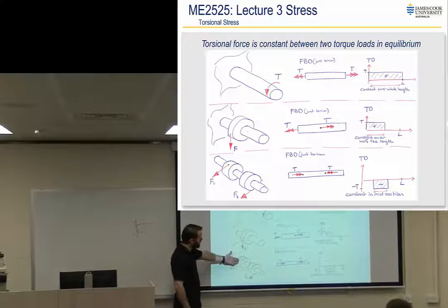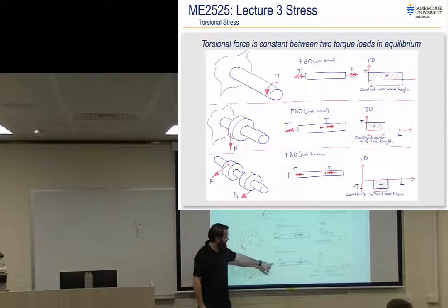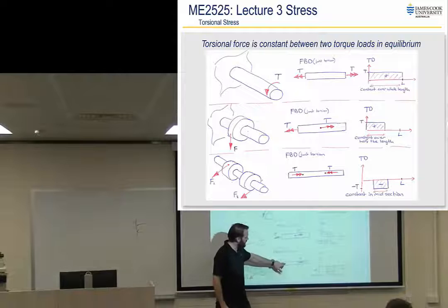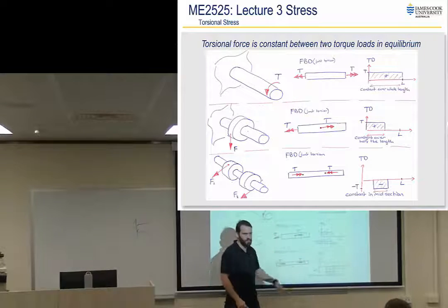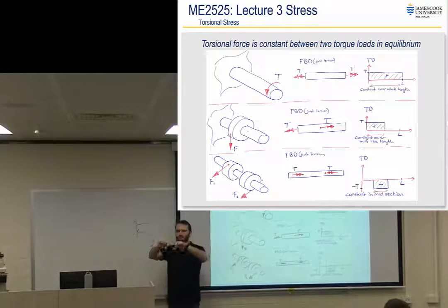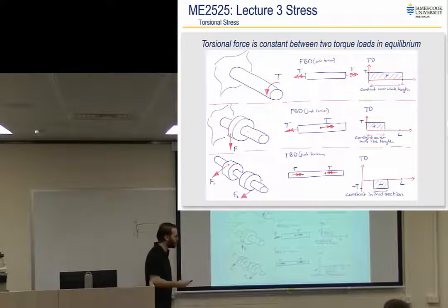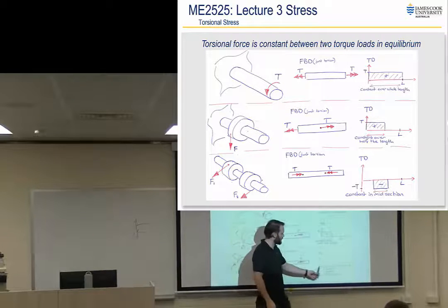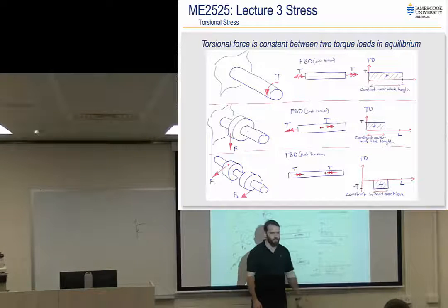This is another example of that. If I have some bearings at each end and then a couple of pulleys or gears in the center there, then we're looking at nothing, and then torque applied, torque throughout this section, torque taken off, and nothing again. So the torque is only between the two applications, or the balancing applications of torque. And so our torque diagram might look like nothing, nothing, nothing. This one's negative, looking at our torques, they go in, and then nothing again.